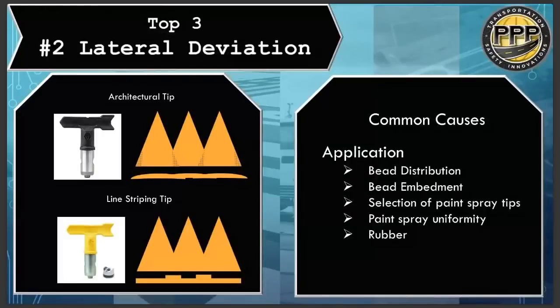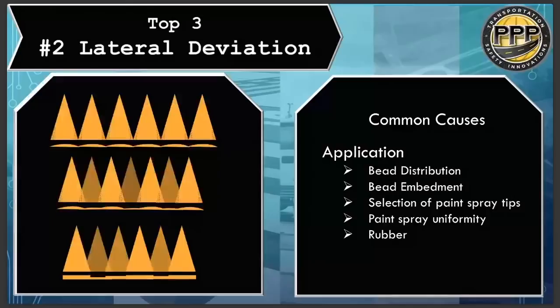The uniformity of that coating is as important as the even distribution of glass beads. It is absolutely as important. As you were probably seeing in some of those pictures, when you have a non-uniform application of paint, some of your beads are sitting high and they are under embedded. They might look brighter than the beads that are properly embedded. Not to mention, a couple of months down the road, the beads that are sitting high are going to come out, leaving that area non-reflective except for the beads that are still there. So you understand that coating uniformity is certainly a big part of this.